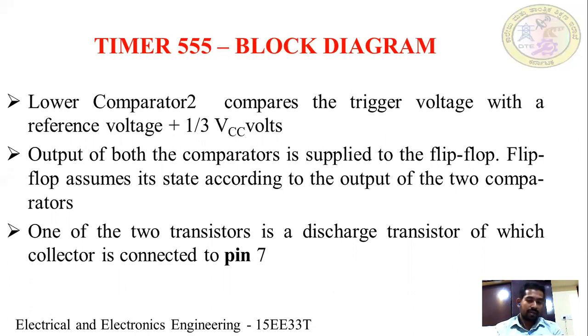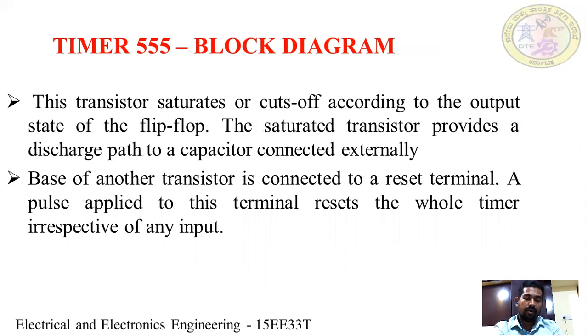One of the two transistors is a discharge transistor, whose collector is connected to pin number 7. This transistor saturates or cuts off according to the output state of the flip-flop.